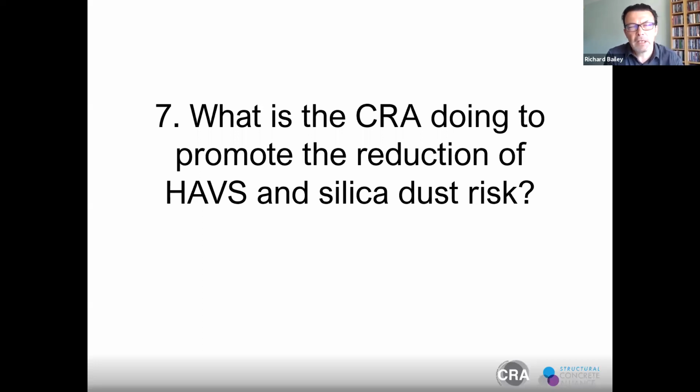In all of this, just linking back to the previous question, we've still got the preparation of a good edge to a concrete repair to achieve. So we must work out how we're going to do that without holding a tool in our hand. And very much linked to the last response on the sustainability topic, let's minimise the amount of material to be removed and replaced in the first place. Reduce the effort. Look at alternative techniques to enhance, strengthen, and protect.